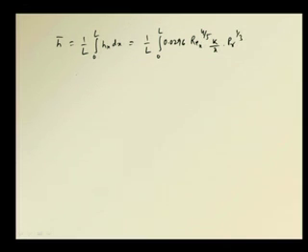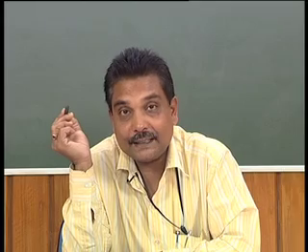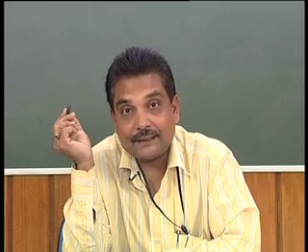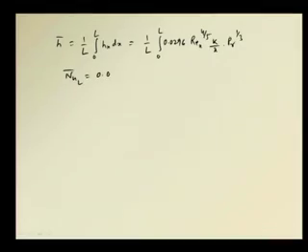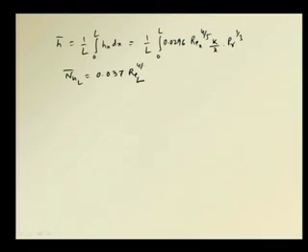And from there we will get the Nusselt number NuL, the average Nusselt number. Again I am repeating that it is based on the average heat transfer coefficient. So, this is equal to 0.037 Reynolds based on the total length, again to the power 4 by 5 into Prandtl to the power 1/3.